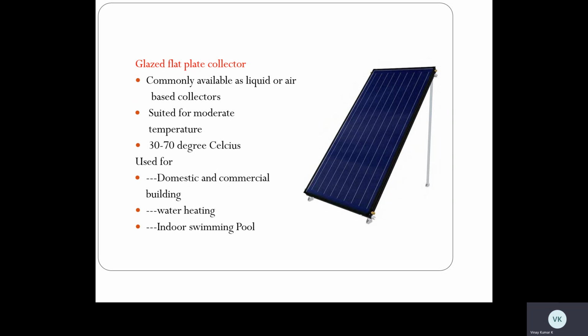That is, wherever we use hot water for domestic, commercial, buildings, indoor swimming pools, in this moderate temperature range of about 32 to 70 degrees, we use glazed flat plate collectors.